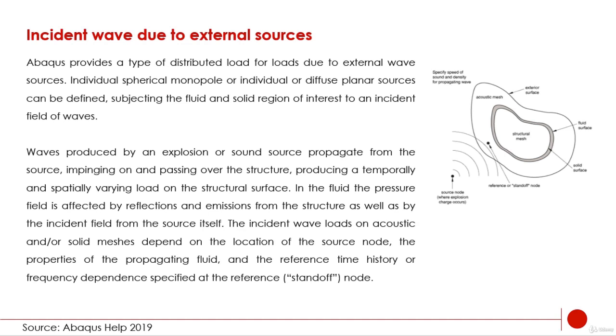In the fluid, the pressure field is affected by reflection and emission from the structure as well as by the incident field from the source itself. The incident wave loads on acoustic and/or solid meshes depend on the location of the source node, the properties of the propagating fluid, and the reference time history or frequency dependence specified at a reference, which we call a standoff node.